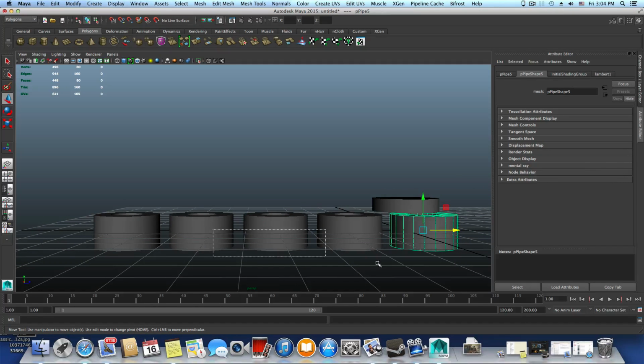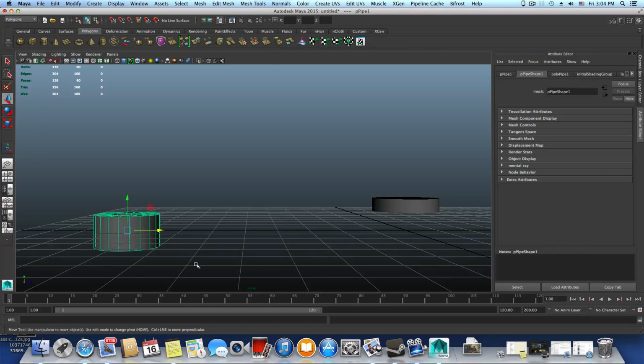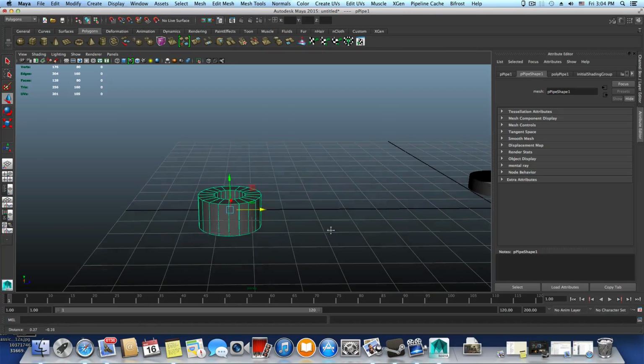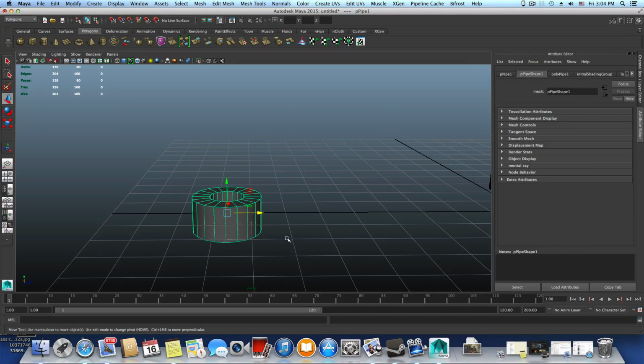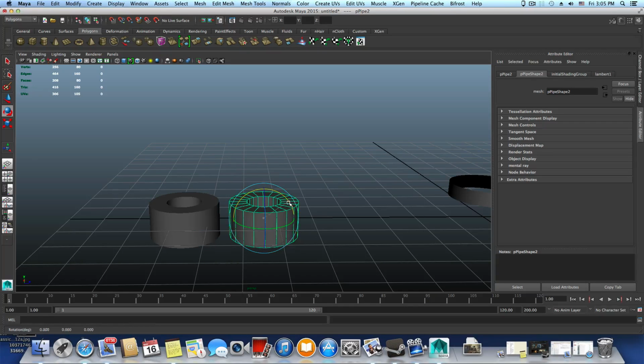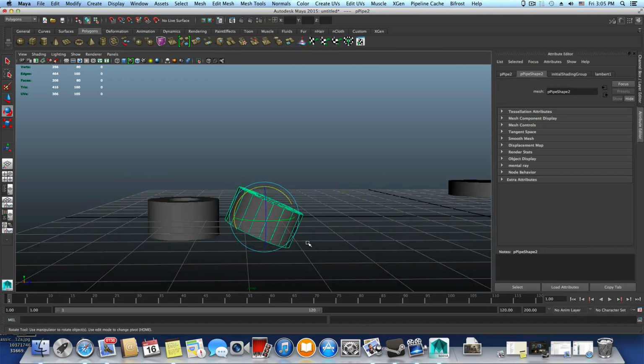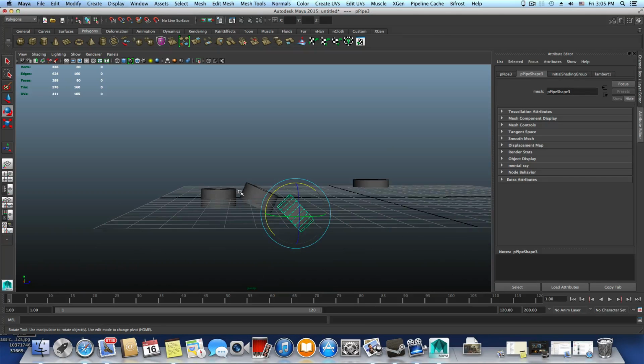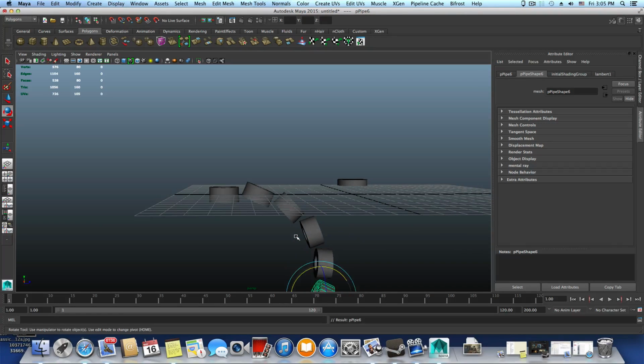Now, with that in mind, you can also grab this one. I mean, I deleted the rest. I'm gonna hit Control D for the first time, move it over here and add a little bit of rotation to this. So now, if I hit Shift D, it will use the same pattern, moving it a little bit to the right and rotating it a little bit. So it's rotating it, and as long as I continue to hit Shift D, this is what will happen.